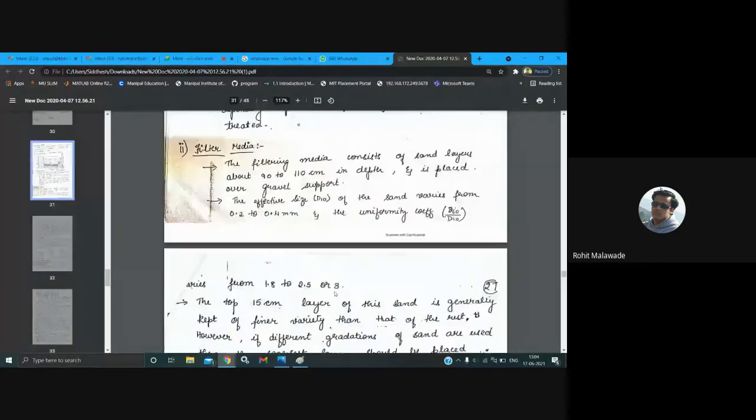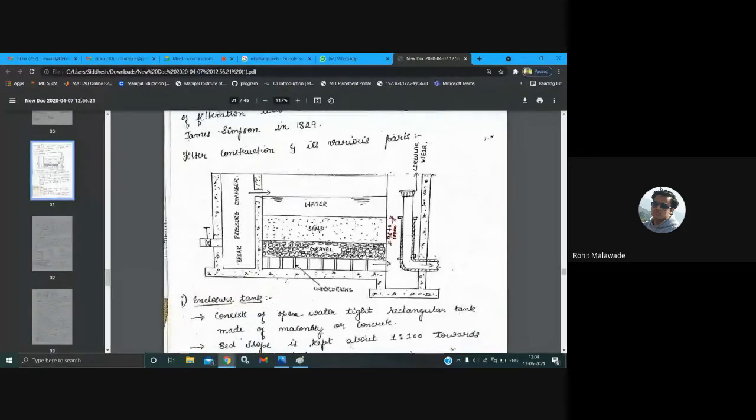One more problem you are going to face in this top layer is, since we are going to remove very fine suspended particles at the top layer itself, there will be the possibility of generation of a sticky material, because this fine sand sometimes has some organic elements, say organic microbes or some very fine egg shells.